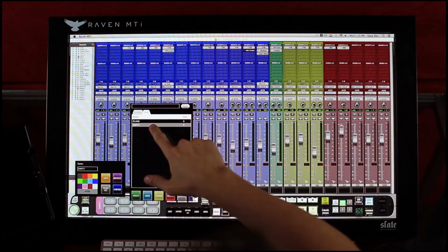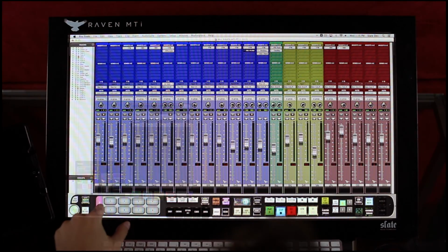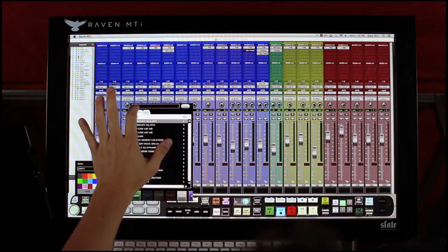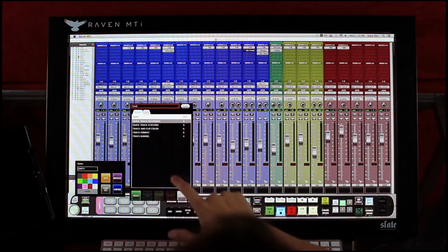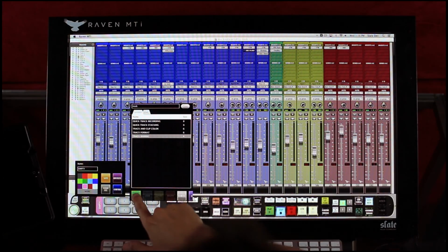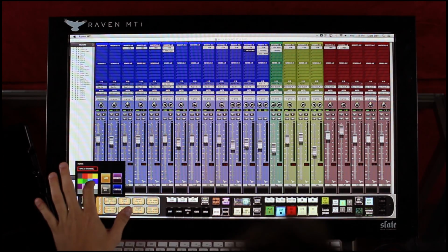To add a saved batch command panel to an empty batch command panel, press and hold the label area of the batch command panel until the dialog window appears and hit Quicklist. Search and select the batch command panel you wish to load and confirm the size of the panel matches the Quicklist item selected by reviewing the size column. Once confirmed, hit Select. Now, just name your batch command panel and give it a color. Then hit Confirm.